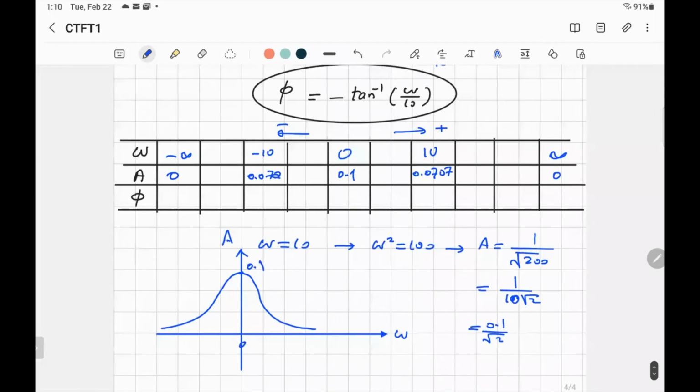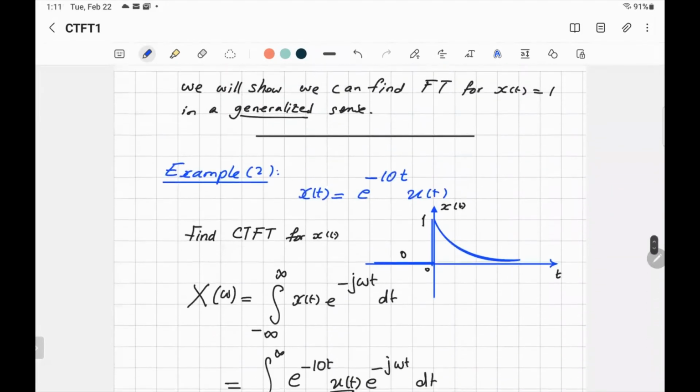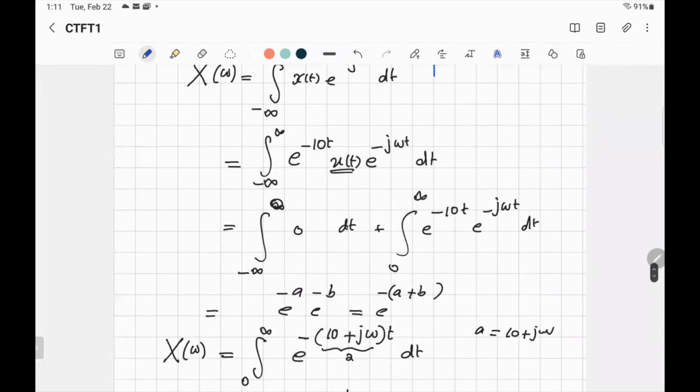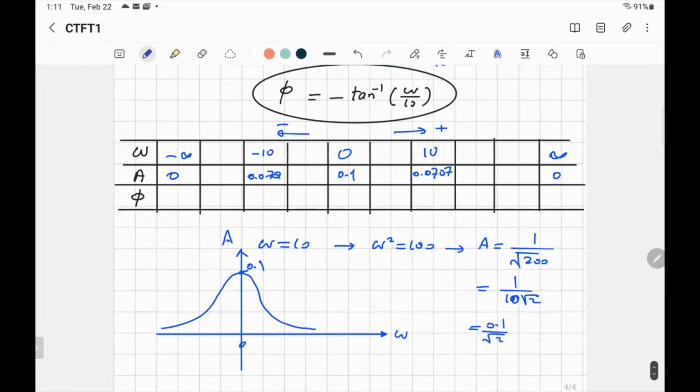And that's why, when you get the maximum value, of course they can improve this filter by what? By adding gain. You don't want 0.1 to be the gain. You want a gain equal to 1. So you multiply this by 10. It would be like 10e to the minus 10t, which is good. Why? Because it makes the DC gain 1. It means no decrease. The gain is 1, whatever goes in comes out. And every time the frequency increases, it will decrease.